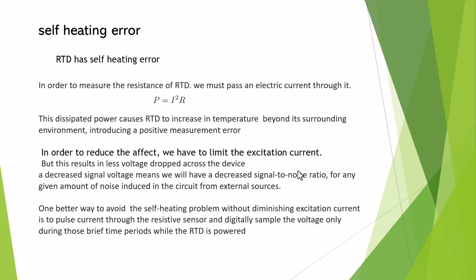Today we just talk about how to simulate RTD. We want to test an RTD on a temperature transmitter. On site, it's not always possible to use a real RTD for testing, so we can use an RTD simulation to do this job and figure out whether the temperature transmitter is good or not.